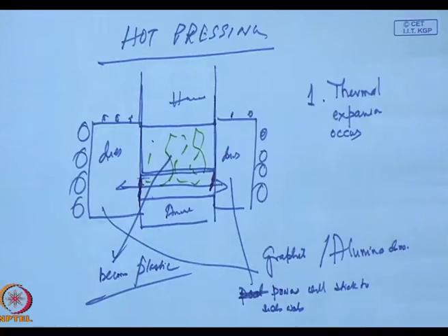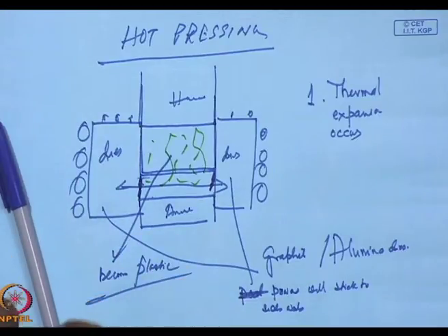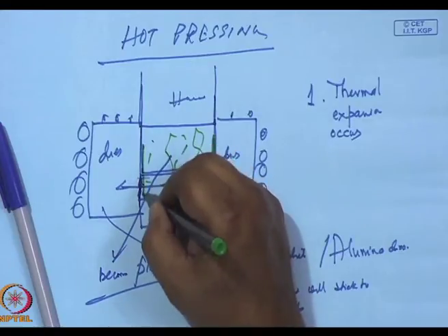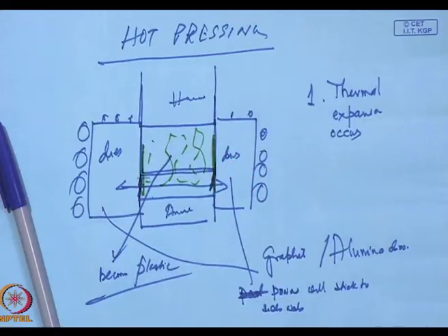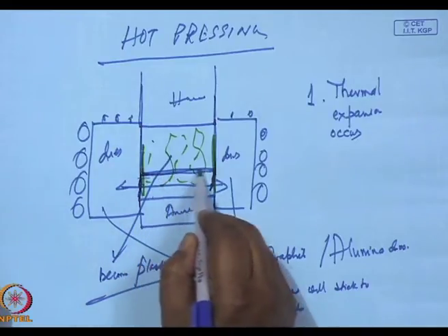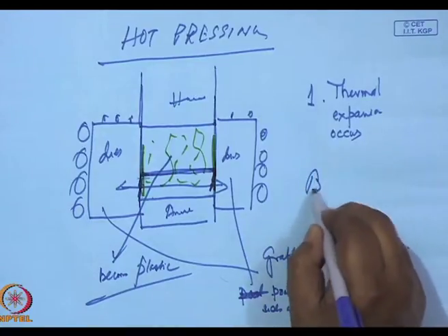Boron nitride is a material which was developed by Alcoa, but they did not train people properly. What is done is, before anything is poured in, a thin layer of this powder is used so that the walls are coated with boron nitride.